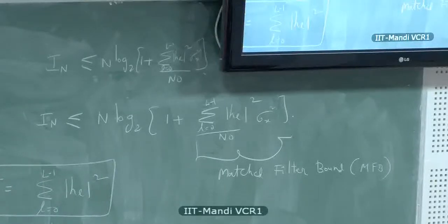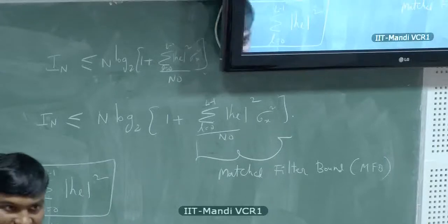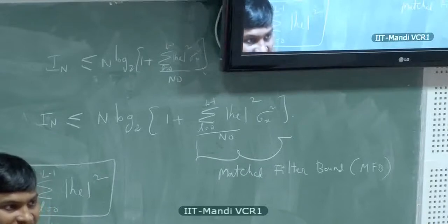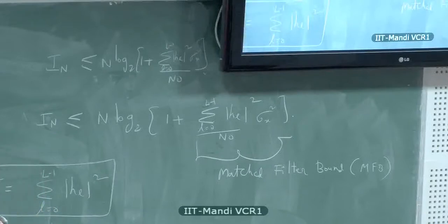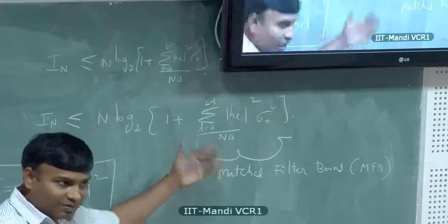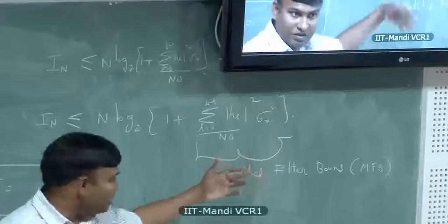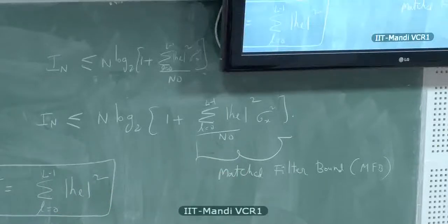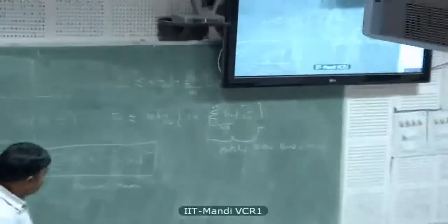Well, in time domain, the way you apply this matched filter bound is, if it is single carrier transmission, you send a single symbol and you collect copies of that symbol and come up with some sort of processing to arrive at this. Basically, it's an ISI-free channel. Whereas in OFDM, to arrive at this matched filter bound, you probably don't do a single shot transmission.